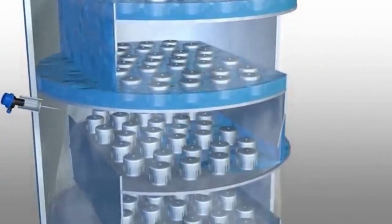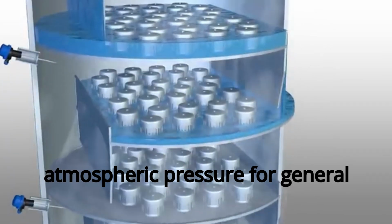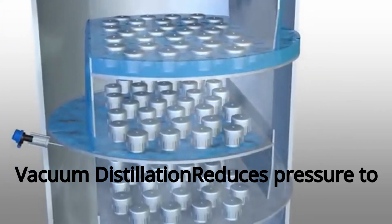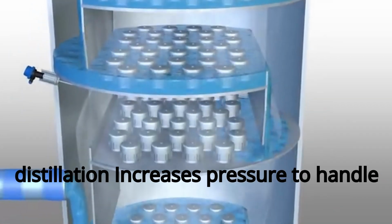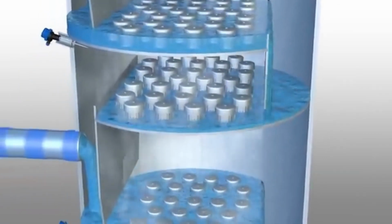B. Pressure. Atmospheric distillation. Operates at atmospheric pressure for general applications like crude oil refining. Vacuum distillation. Reduces pressure to lower boiling points, used for heat-sensitive components. High-pressure distillation. Increases pressure to handle gases or high boiling point mixtures.